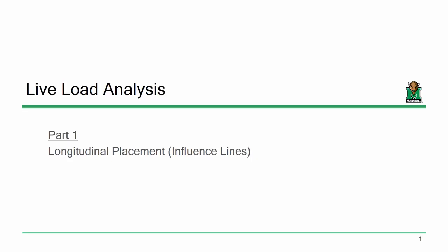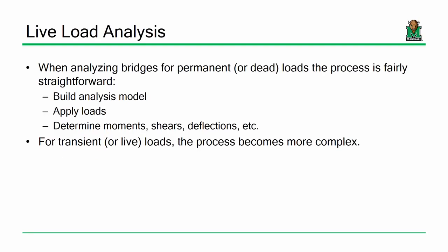So let's start off with longitudinal placement, and that means talking about the concept of an influence line. Now, has everybody heard of an influence line before? I've got to believe that you've talked about influence lines in structural analysis. It might have been a while. That's okay. We're going to have a quick review. So the idea behind this is when you're dealing with permanent loads, structural analysis conceptually is really easy. Here's the model, put the loads on it, get the response. That's all there is to it.